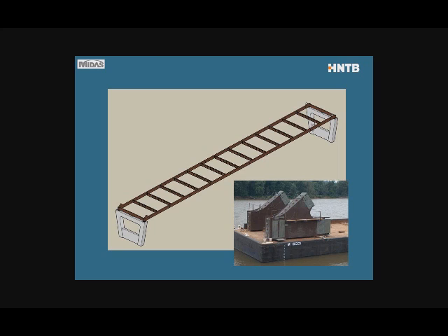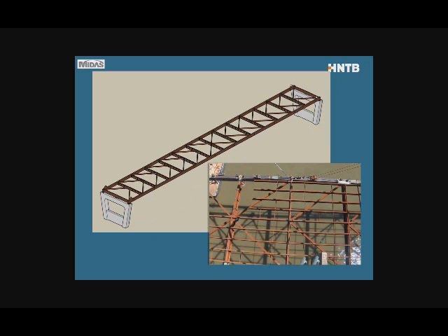You can also see at the end of the front knuckle joint those gray patches. This is where the end floor beam is bolted into the knuckle joint, and it needed a lot of bolts just to transmit the jacking force when the jack is applied. So a very, very complex joint, but it's crucial for the structure. It's also through that joint that the arch rib gets stabilized a little bit.